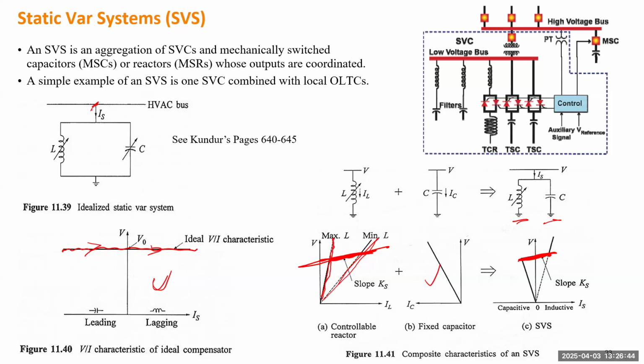But this system has a lot of drawbacks. If you can make sure to operate within this operating area, that can guarantee the voltage to be controlled around the setting point. But what if you reach the limit? You are going to follow this line or this line, and that will suddenly change the voltage. Imagine you involve this system in your automatic control, and under normal condition, the voltage will be very close to nominal value. But sometimes it just reaches the limit, but you don't know. If you apply further control, it will suddenly drop.